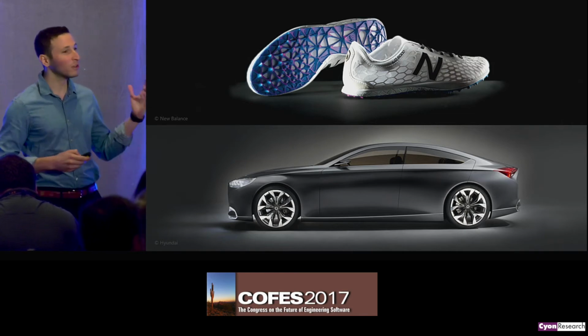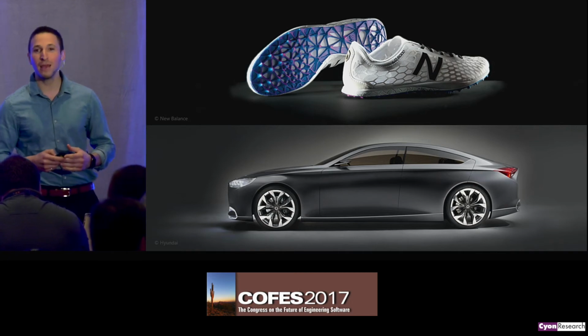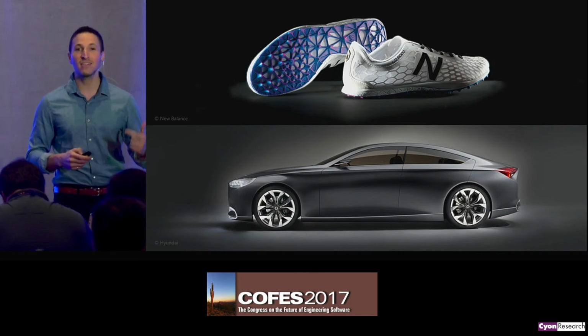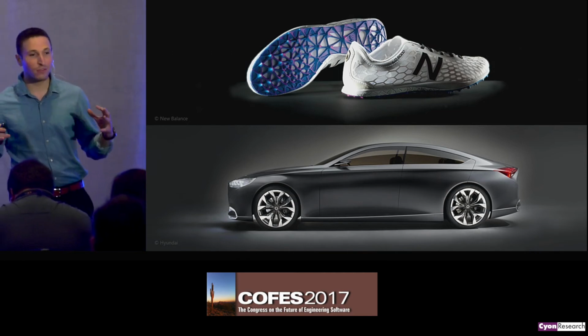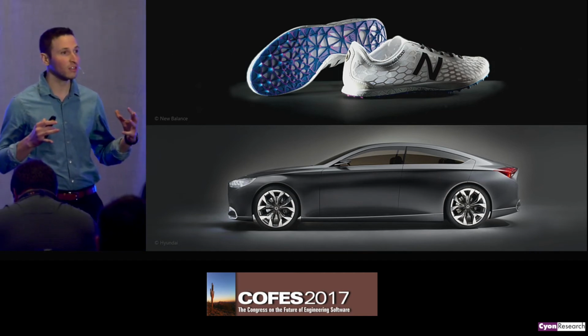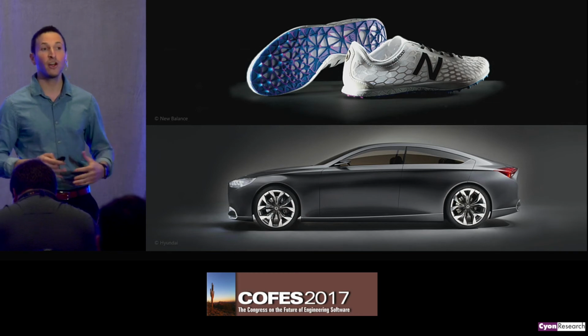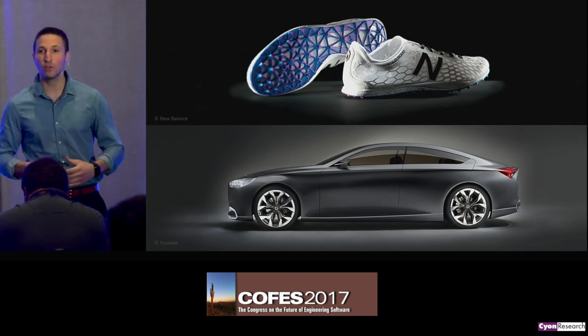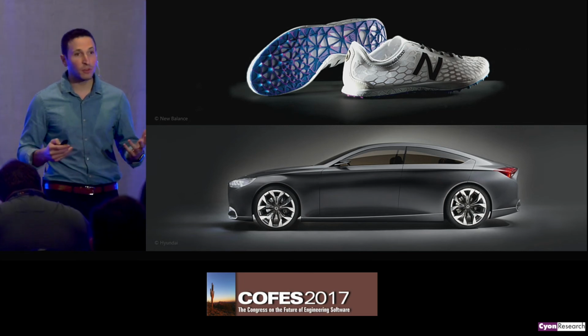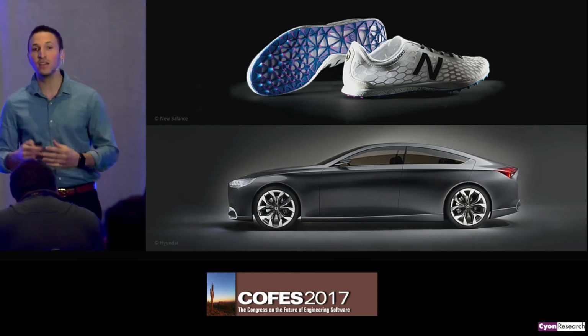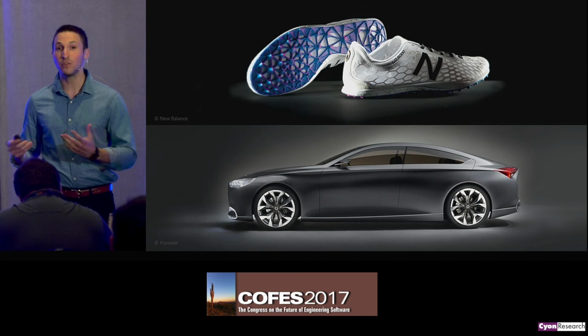And another one is the traditional automotive space, where the name of the game is, of course, reducing part count and simplifying assembly. By making integrated assemblies that are additively manufactured and multi-material assemblies, we can reduce the number of parts that go together, no fasteners required, and of course make really simple but complex assemblies. A couple examples being integrating suspension into a chassis, as well as integrating seating into a chassis.